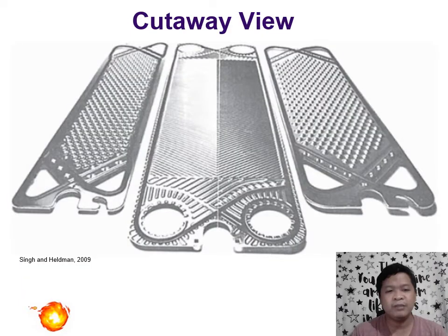So as seen in the previous video, when you look at the cutaway view of the heat exchanger, it's filled with a lot of patterns that increase the surface area, makes the flow more turbulent, and in total, hastening the heat transfer as compared to when you have the flat plates of stainless